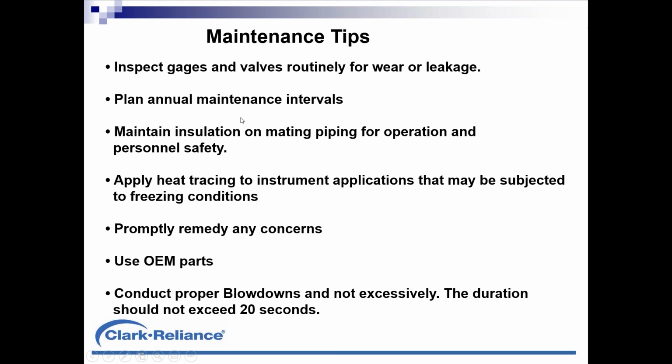So plan your annual maintenance intervals, document your repairs to track them and see what could be done to make improvements. Maintain all your insulation on all your piping leading up to instruments, for operation purposes as well as personnel safety. If your application is subject to freezing conditions, we'd recommend heat tracing on all the piping and the instruments so that you don't suffer any damage to those instruments in freezing situations.